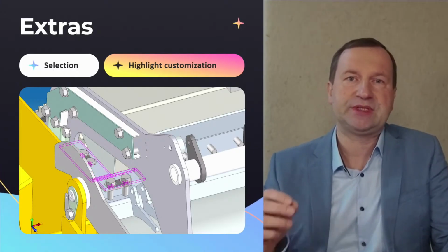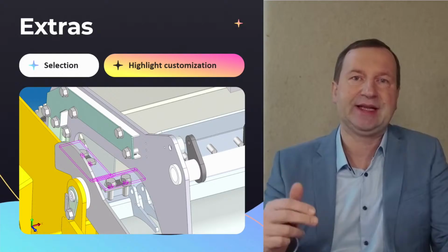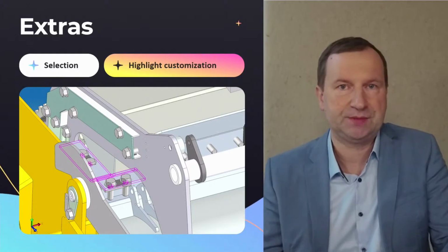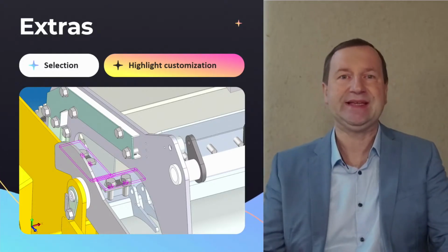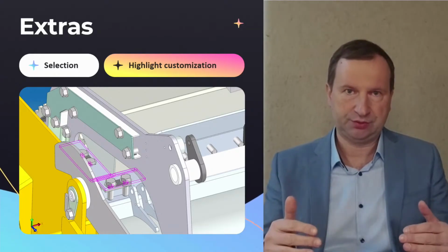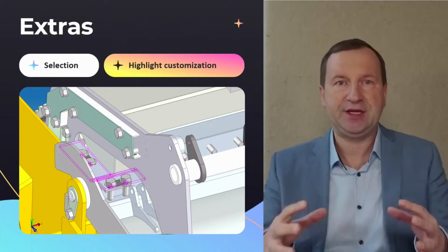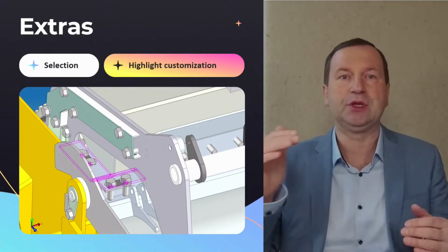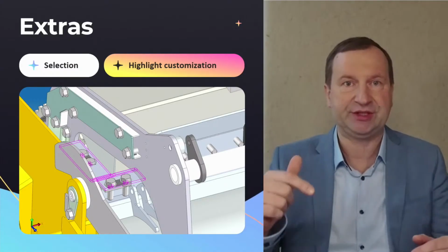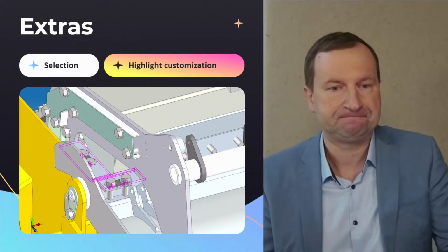It's important to note that customizing highlighting styles may increase resource consumption. For example, if a scene is rendered in shaded mode, where edges or user lines aren't loaded for rendering, adding edges to the highlighting style will load them into the rendering engine, increasing load.